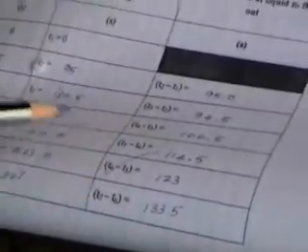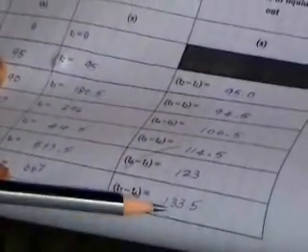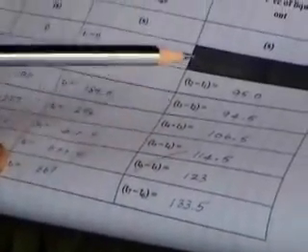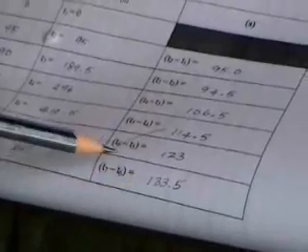What calculation has to be done is also given directly here. You just need to follow the calculation. That is, from 40 to 45, the timing is this. From 45 to 50, this is the time taken, etc. One thing you will note is, as you keep going down, since the pressure head reduces, the time starts increasing. You can see the time taken for every 5 cc to flow goes on increasing. Please observe the pattern here.